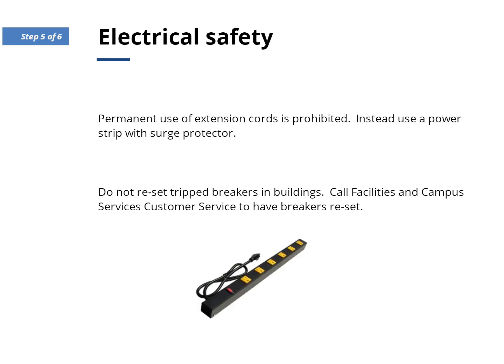Basic electrical safety. Permanent use of extension cords is prohibited. Instead, use a power strip with a surge protector. Do not reset tripped breakers in buildings. Call facilities and campus services customer service to have all breakers reset.